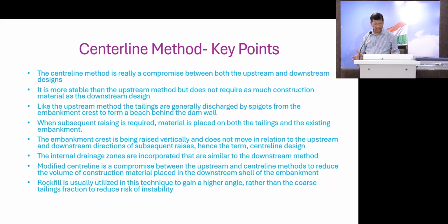And this is more stable, definitely more stable than the upstream method. I have been involved with many upstream tailings dams. While raising, they change it. It was initially started as upstream, but while raising, they changed it to the central line method.